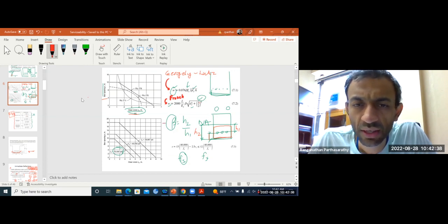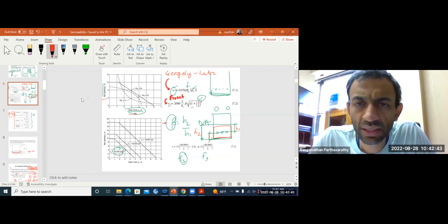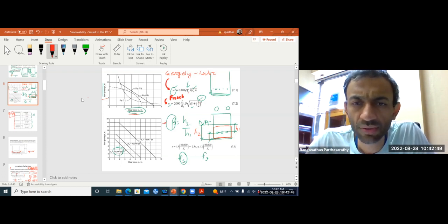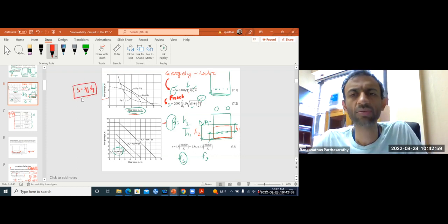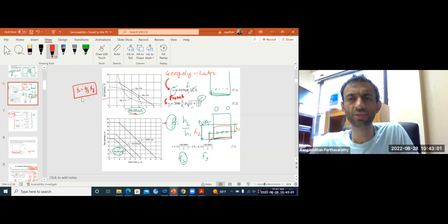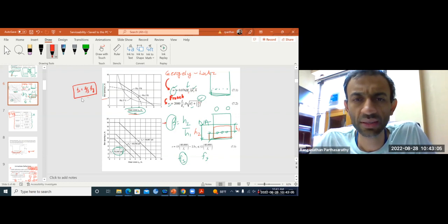Fs is the stress developed in the steel under service load. If you're not doing an exact calculation, you can assume Fs is 2/3 of Fy, that is, under service loads the stress in the steel is 2/3 of the yield stress.